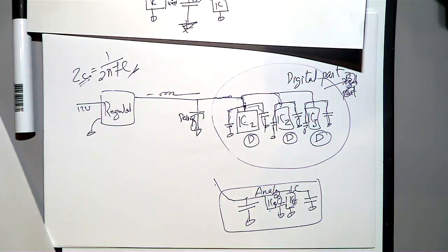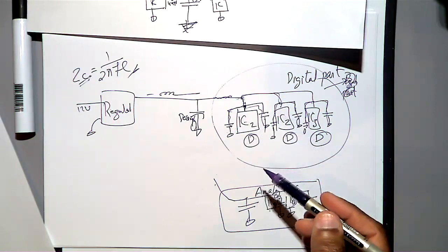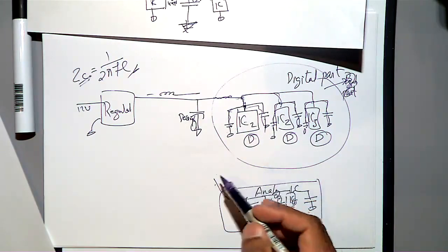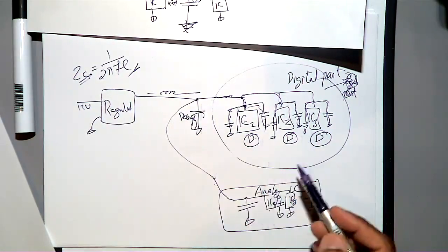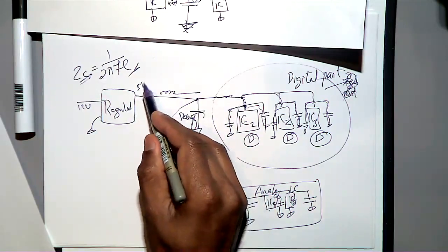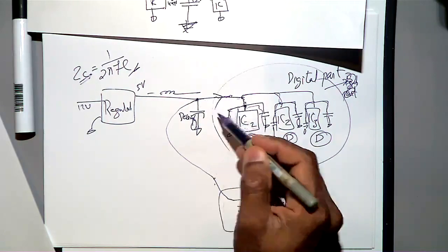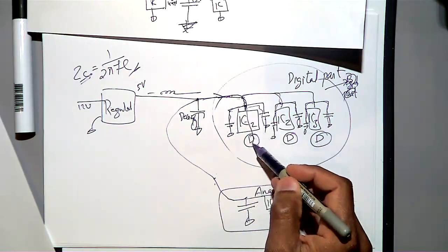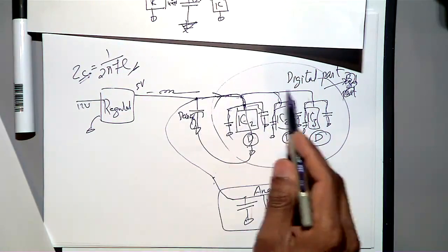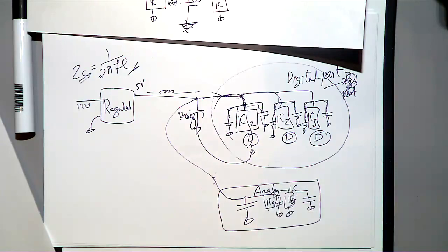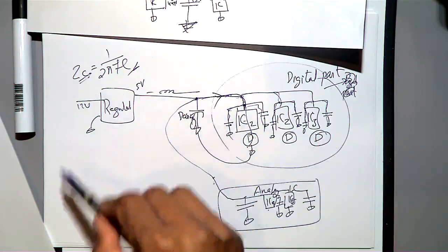But when you connect this one, I wouldn't say that this will completely avoid all the noises. See, this is a decoupling capacitor, so maybe I can connect this to here, so that here you are getting 5 volt, and at the moment your circuit is closing here. The current is going and passing through this one, then it's a ground, and then the return is here. So this is your local power supply for the ICs. Same with analog. The digital part you will be putting here, the analog part you will be putting here, then you got a common ground.